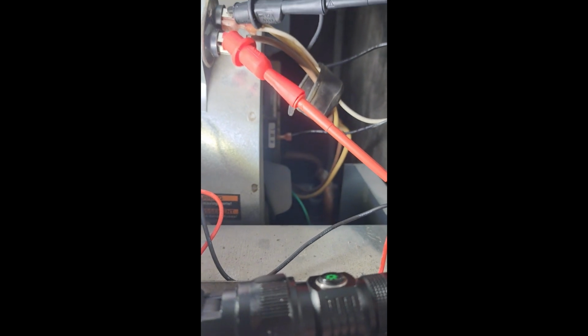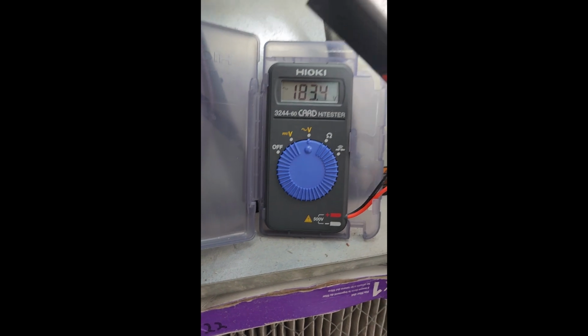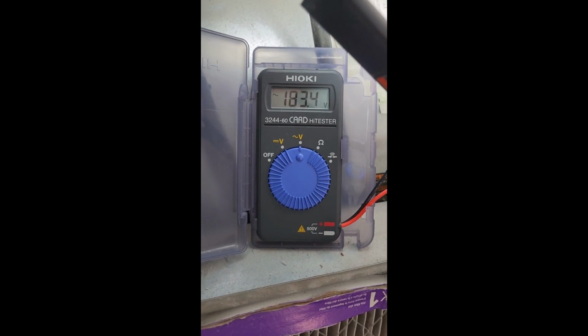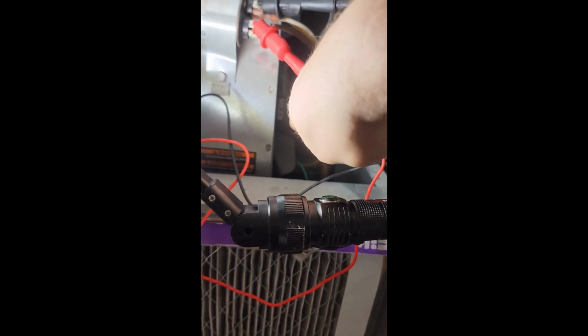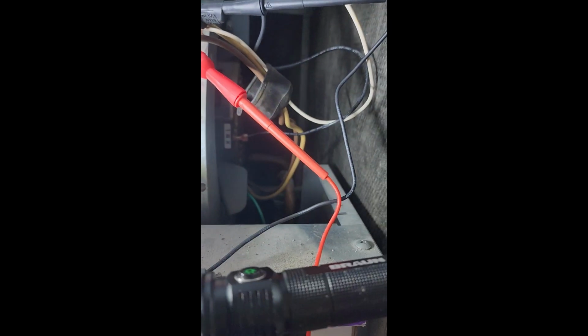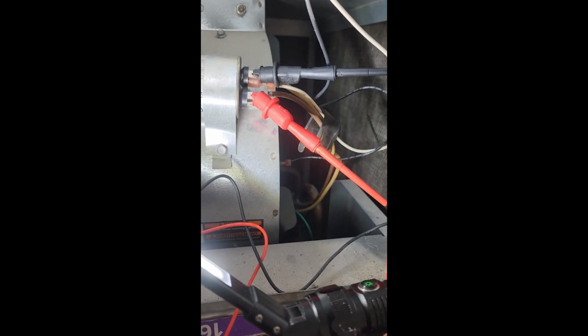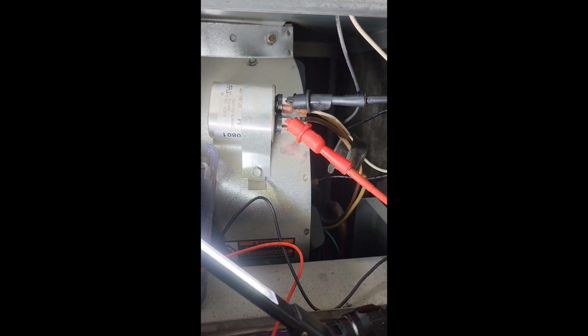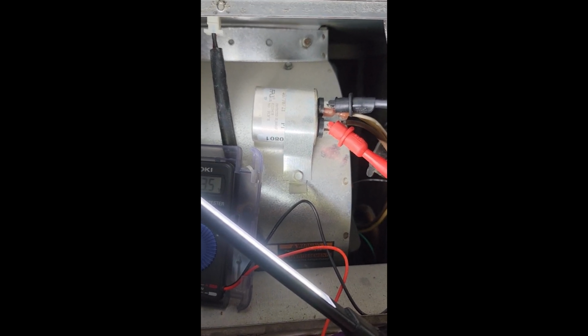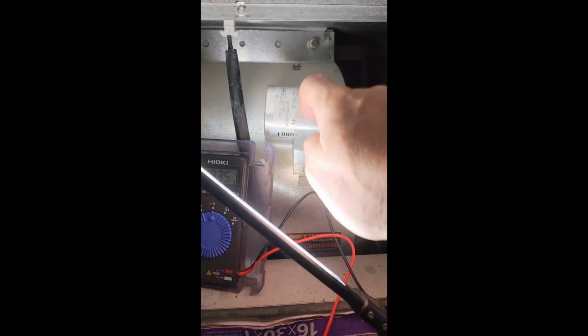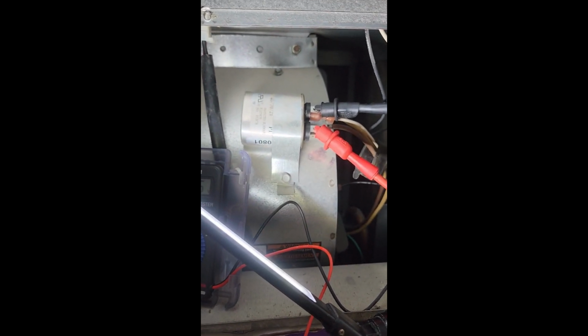All right, so unfortunately, moving the wire into the other positions did not do anything. But one thing I did notice, so I have the meter back on the capacitor here. So here we are at 183 volts, where when we actually measured the wire from this leg as well as from the black wire there, we were at over 200 volts. So before we conclude that it is definitely the fan, I do want to do a little bit more digging into this little capacitor here. So let's continue.